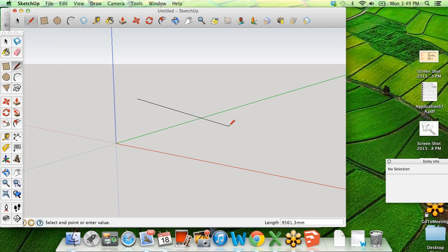And it's not always apparent. If you guys know parallel, it means side by side so that the lines never cross. And you can tell if the line that you're going to make is parallel to the different axes depending on the color it is. So here it's parallel to the green axis, to the red or the x-axis, and to the blue or the z-axis. But if you look at this green line, those don't necessarily look parallel, right? You wouldn't necessarily guess that. I'm going to click again to finish my line, and I'm going to press escape because I don't want to build another line.